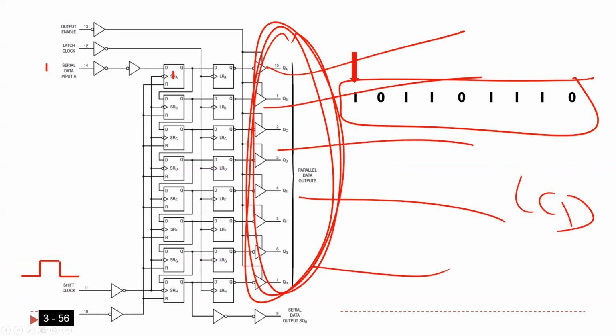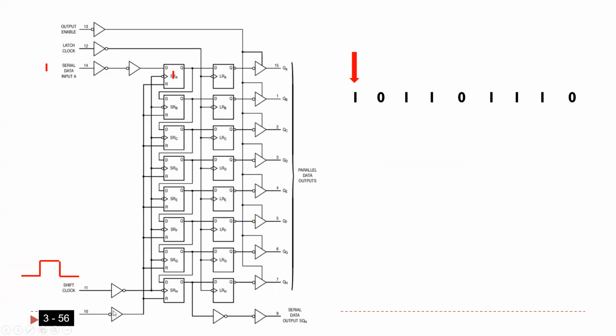If I want to do something like that, how am I going to do it? You have to make a for loop 8 times. You will see in the code, I did it. In every iteration, I'm going to input one bit. In the first iteration, I'm going to do this one. Second iteration, that's exactly what I'm going to do. Look what happens here, guys. This is the first iteration in the for loop. I'm going to put 1 here, as you see. Then I'm going to give it a clock. Once I do that, you can see the 1 is here.